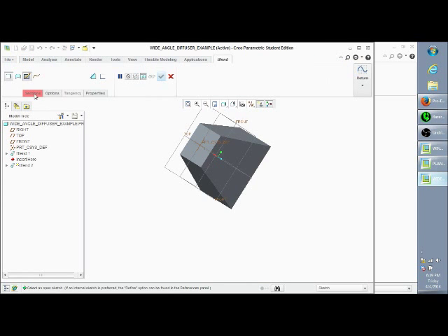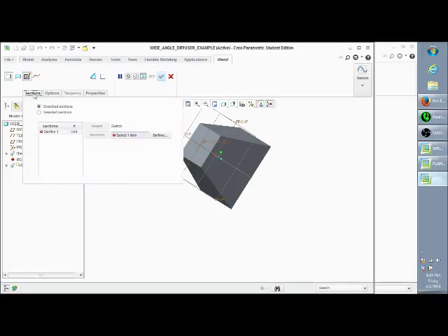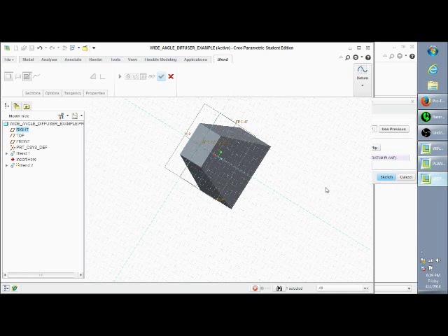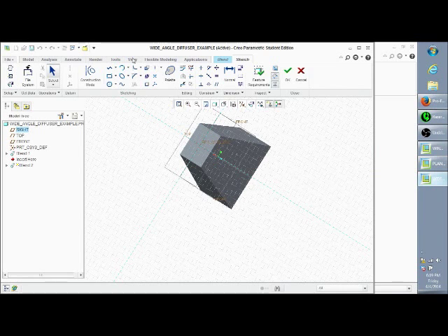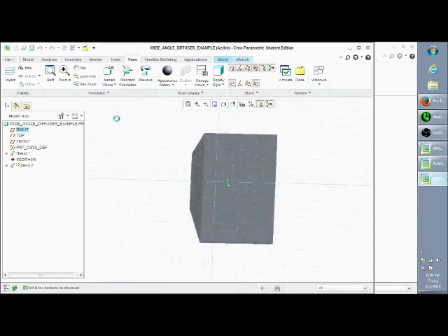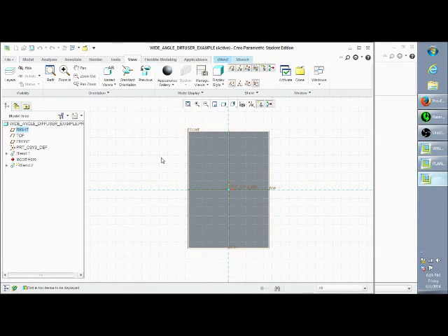Wait for it to pop up, and now we have this sections thing. So we're going to still use this sketch sections selection, and I'm going to go to define. When the plane pops up, you can select the front tab. I'm going to select this surface, the smaller surface, and the right datum is still okay. So we can go ahead and select sketch, and I'm going to set it up so that I can see from the front plane. So named view is front.